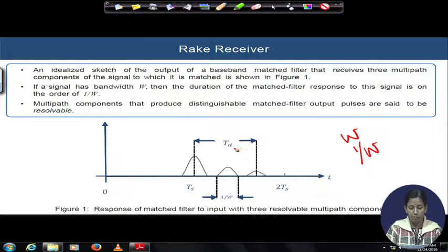Remember one thing, we have considered that T_s is the duration of the symbol, and τ_d is the maximum delay that we will consider for the analysis. Another important point to notice here is that if this total delay is less than the symbol duration, then this multipath spreading, or delay spread, and hence the dispersion of the signal, won't contribute to any intersymbol interference, because it won't overlap with the next symbol coming up at the moment 2T_s.